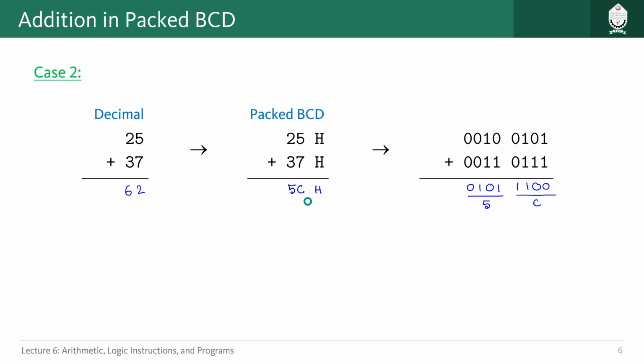How to solve that? What you have to understand here, just by looking at the result, we can understand the issue is coming from this lower 4-bit stage. For this lower portion, the value is C, which is not a correct BCD representation. For BCD, the valid range is from 0 to 9. So somehow for this particular value we are getting the issue.